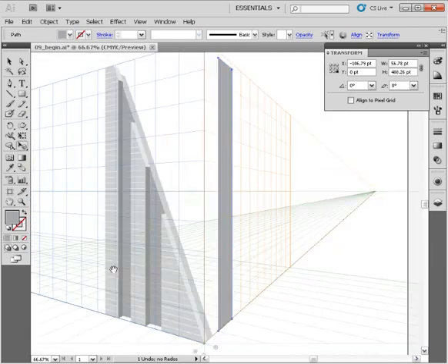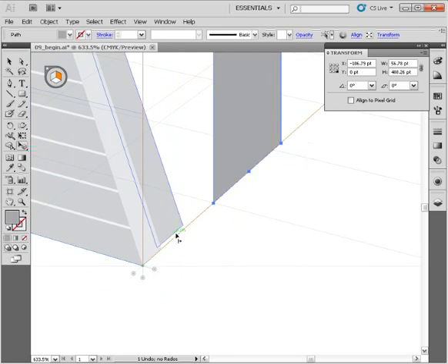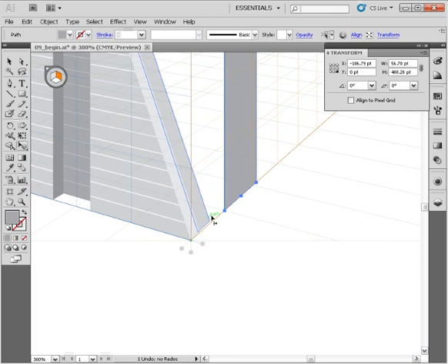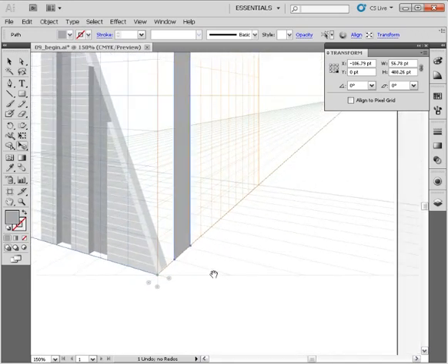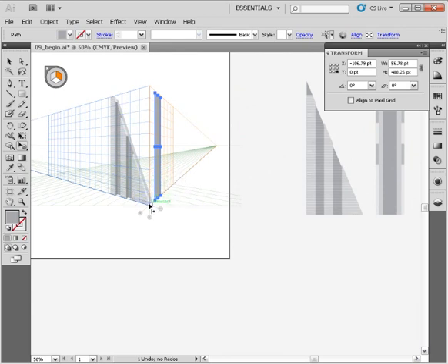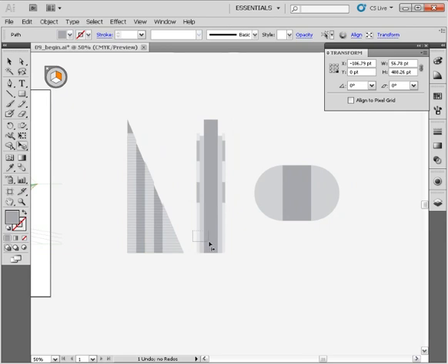Alright, so we've got this in position, and we've got a little bit of a challenge. We need to get it inset here just a little bit, but we also need to know where to position it in relation to these other two pieces, so it appears to be snugged up against this one when we inset it. I know that I can get that lined up perfectly on the 0, 0 point, or our origin, so I'm going to select these three objects and check out their width. Selecting these 3, it's 1.2069.